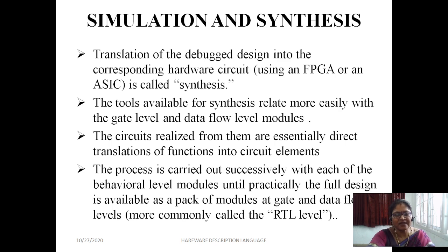Next one is simulation and synthesis. The translation of a debugged circuit into a corresponding hardware language is called synthesis. By using FPGA and ASIC, we have to convert our hardware circuit through synthesis. The tools related to synthesis work more easily at the gate level as well as the data flow level module. The circuits realized from them are essentially a direct translation of function into circuit level. We have different packages available. The gate and data flow levels are combined and commonly used as RTL level, that is, register transfer level description.